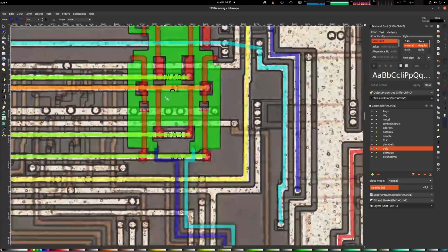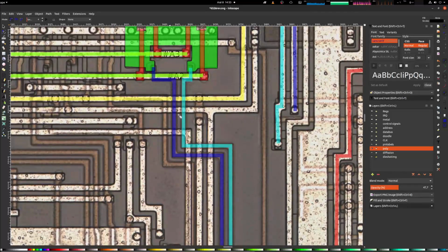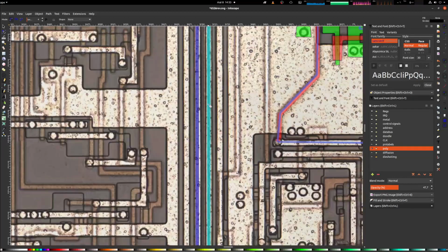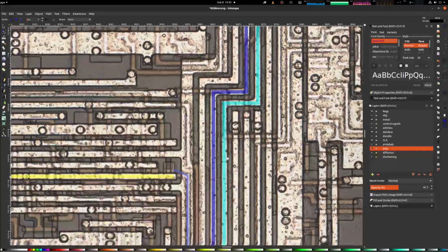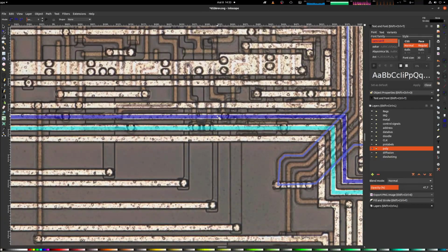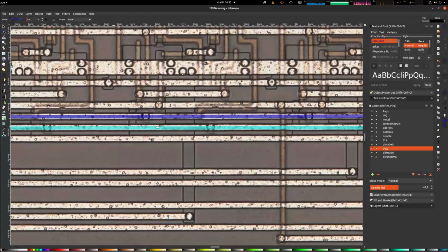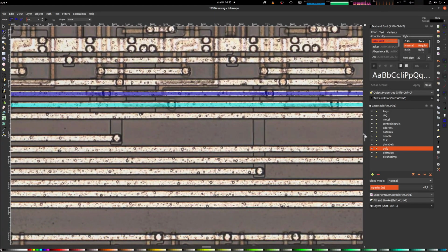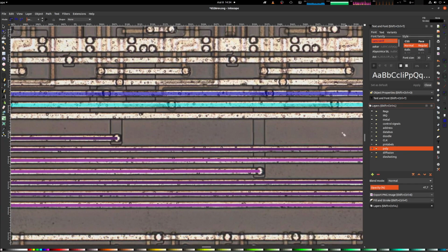So let's see where those read and write strobes, they are called strobes, go. Whenever one of these two fires, or goes high for that matter, they will actually read or write to that register. So here you can see it taps off these lines. So this means the register is over here. And interestingly, when I bring in the data bus, you can see read or write will then bring data into this data bus, from the register.